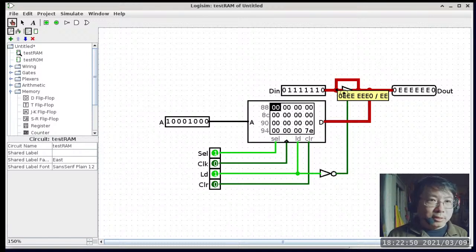In reality, you have transistors trying to fight each other. So you have basically one side having the P transistors connecting a conductor to VCC, which is the positive voltage, and then the other device has the N transistors connecting to the ground. So now you have a very short, low resistance path from the positive voltage all the way to ground, only going through the transistors.